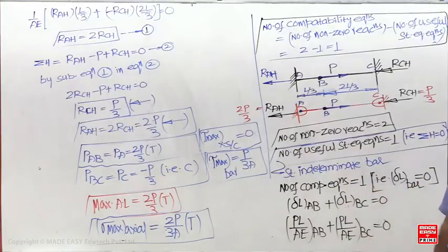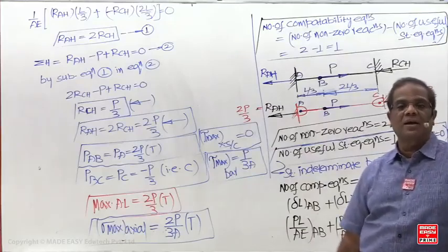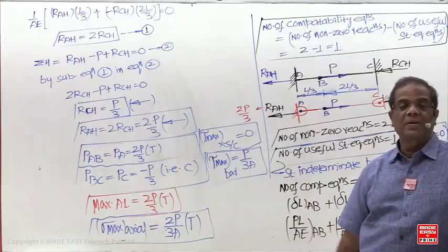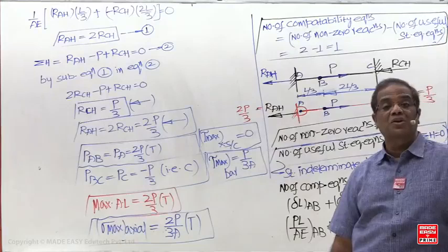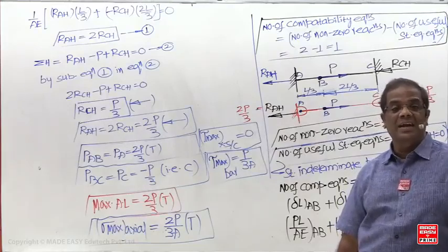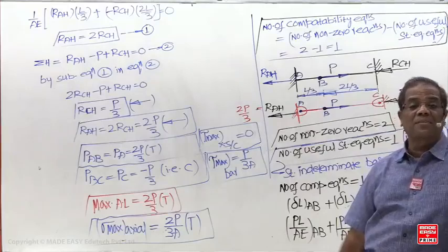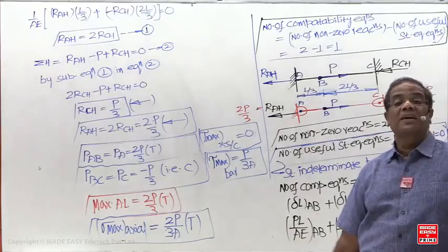The same concept is going to come in beams. At that time the deflection equations are required. Propped cantilever beam, fixed beam, and continuous beam are all statically indeterminate. In that case the reactions are calculated with the help of compatibility equations. There you go for slope and deflections.